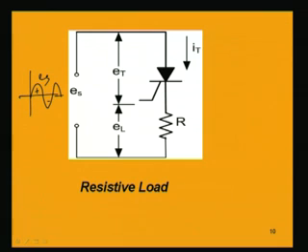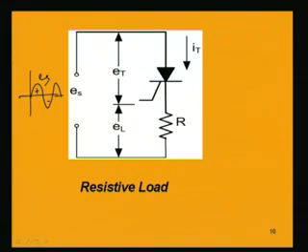So, in the positive half cycle, by means of this triggering voltage at the gate, we are not now discussing the methods of triggering, we are assuming that a triggering voltage is applied at the gate to fire the thyristor at an angle of alpha. The delay angle of alpha is maintained. What method of gate triggering is used, that is another topic of broad discussion. So, we are not going to discuss those methods of triggering, but simply assuming that it is being triggered by a suitable method for getting a delay angle of alpha.